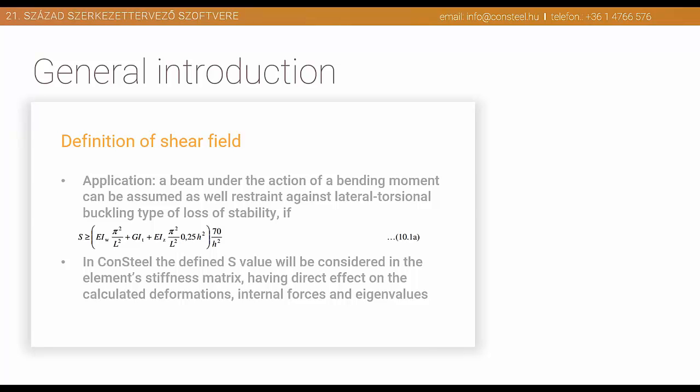And with this complex formula, one can calculate the minimum value of S which must be ensured, applied through the appropriate connectors to the beam, in order to have the chance to declare that once a panel of a certain S has been considered, it is strong enough to provide all the necessary lateral restraint in order to avoid fully the need for stability verifications.